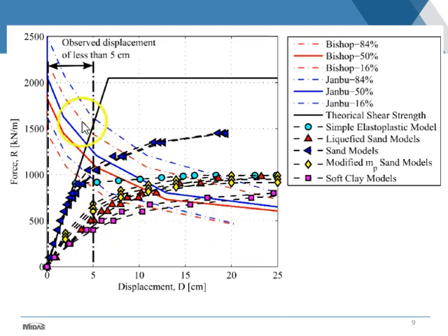If you take a look at, let's say, these curves going down, and here is some kind of uncertainty around that, and you see those curves going like this. It depends really on the procedures you want to look at, but this procedure will probably tell you that the residual lateral displacement is going to be in the order of 10 centimeters. So about 4 inches.